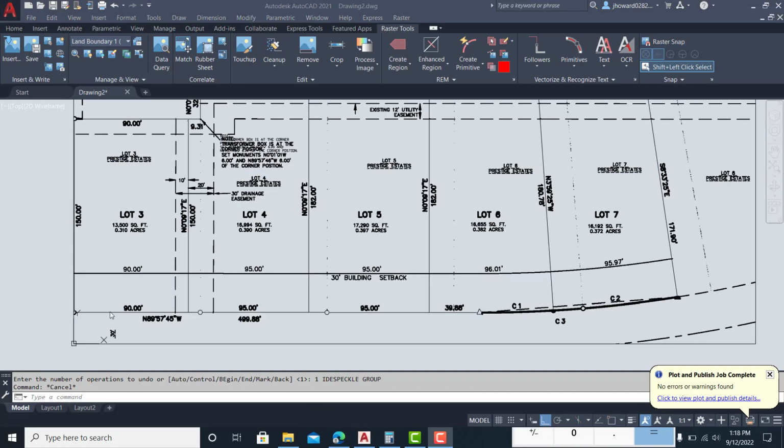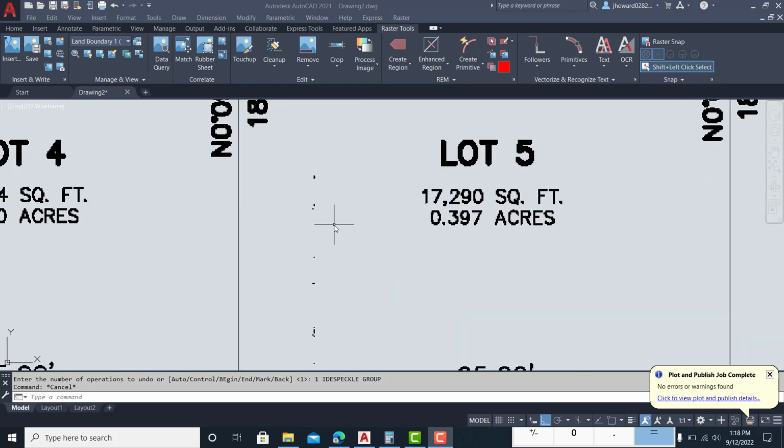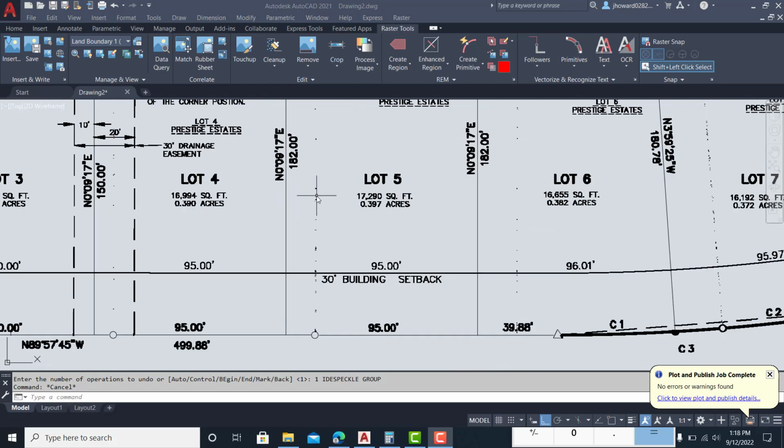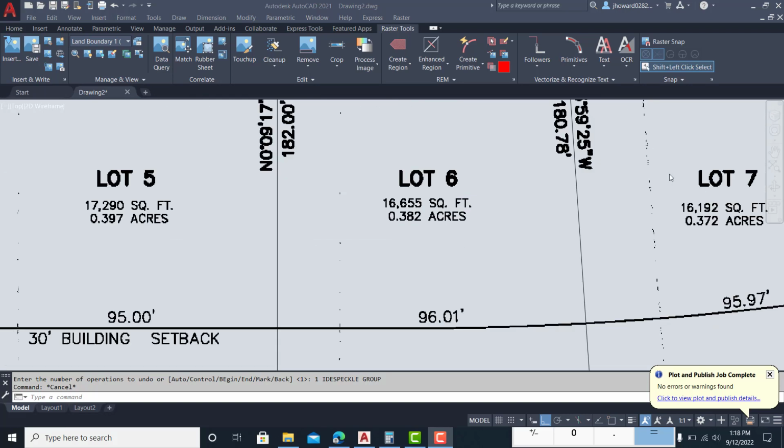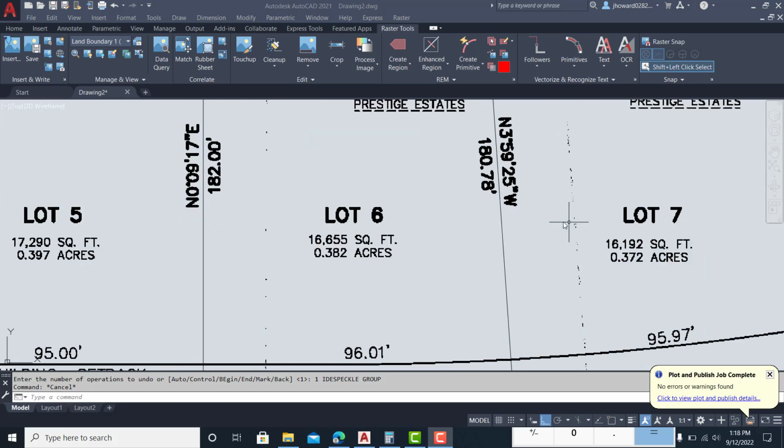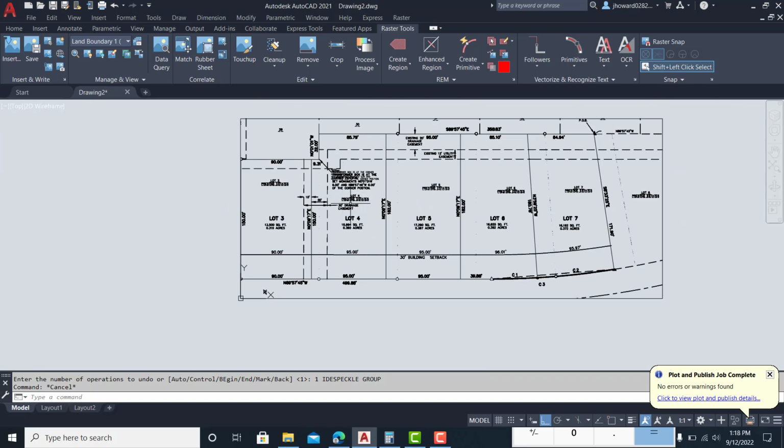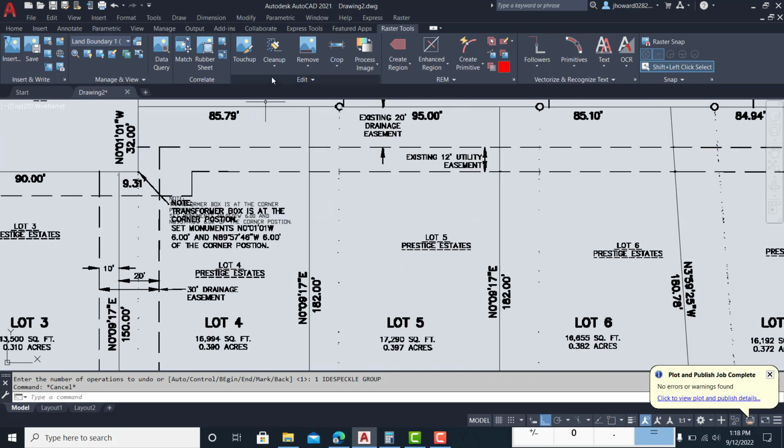All right, guys, we're going to despeckle this thing. Again, we were looking at these little spots, and sometimes you'll get drawings when you're scanning that have tons of little spots and blemishes in them. What you want to do with that is you've got this cleanup tool. Come up here to clean up, and you can go down to despeckle. And most of the time I want to do the entire image. And then it says, what size speckle do you want to get rid of? Well, it's going to do it in pixels.